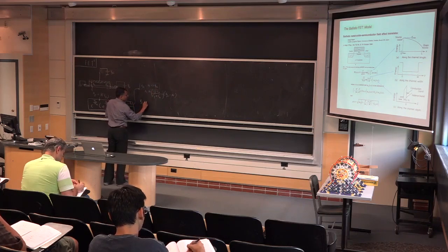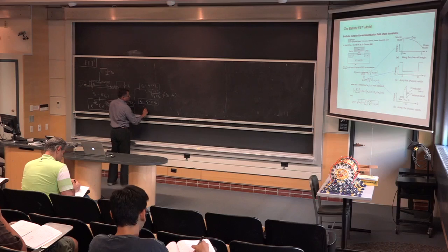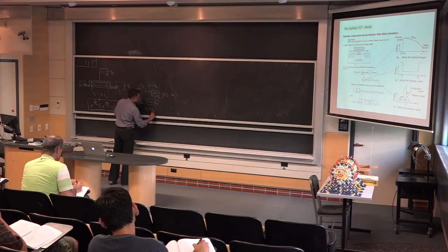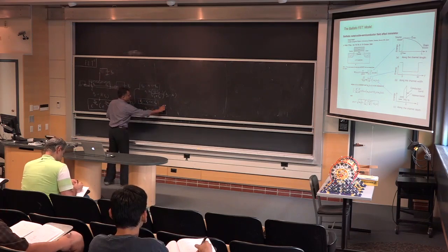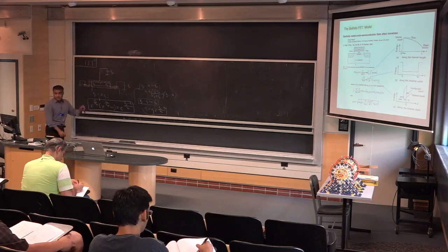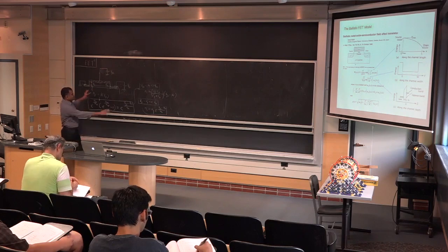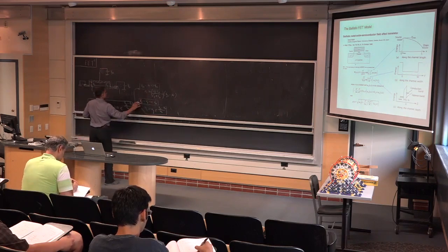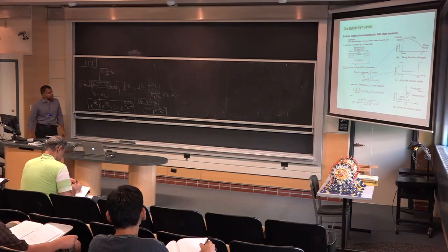And the other extreme was when VGS minus VT was much less than thermal voltage. You're off. Under that situation, the carrier density changed exponentially with VGS minus VT over the thermal voltage, and that's what gave you things like 60 millivolt per decade and that sort of thing. So we did that in the last class. All this is true if this is grounded, and we're just applying a gate voltage and finding the charge in the channel.